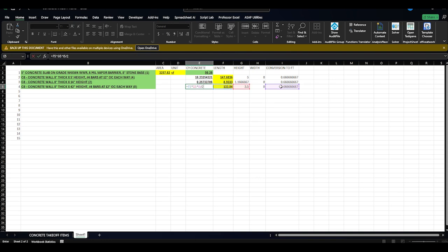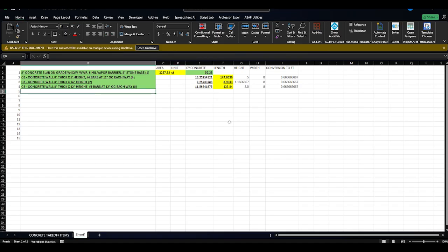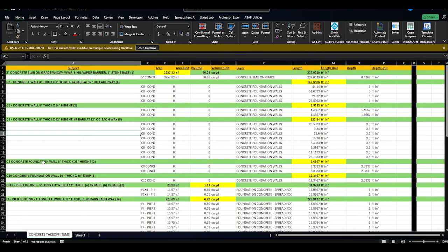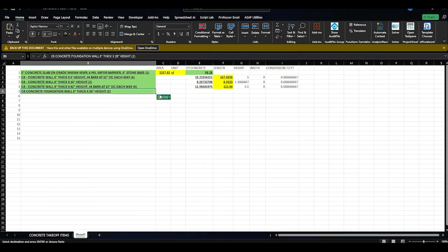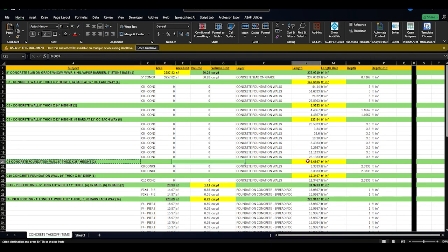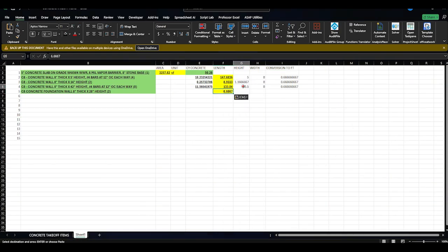Normally, my spreadsheet would be much more detailed and incorporate cost component breakdowns to take into account labor, material, equipment, and subcontractor costs associated with each individual item. In this example, we are only using an assembly unit cost average to get the work item totals individually. The goal of this working sheet in progress is to have the condensed data expressed in terms of the unit that we will multiply by the assembly unit cost in our final layout in the next sheet. You are watching that process unfold down the list for each item in preparation for the finished sheet structure.